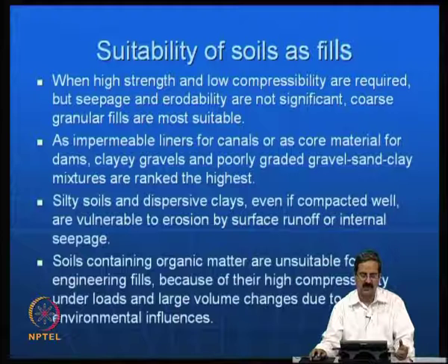So, you can just take coarse granular material if you are interested in high strength and low compressibility. Sands, fine sands or medium dense sands have this sort of behavior, in which you get good strength and low compressibility as well. Suppose you are looking for impermeable liners for canals.